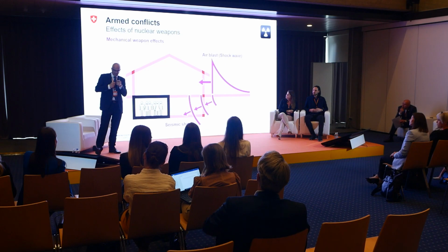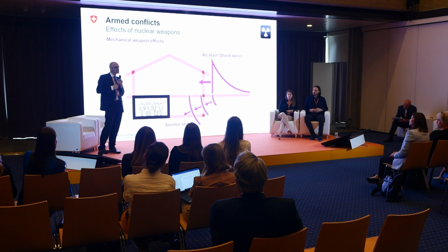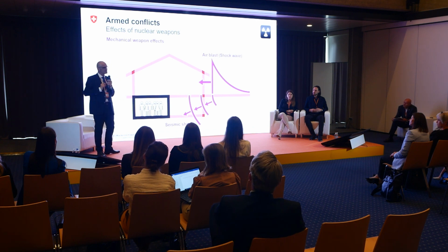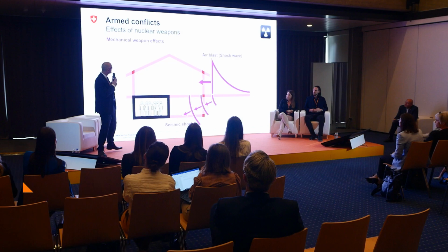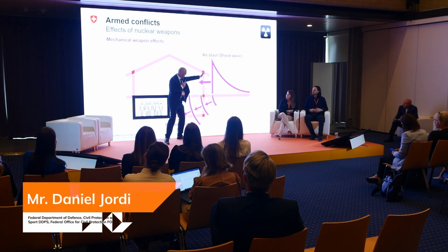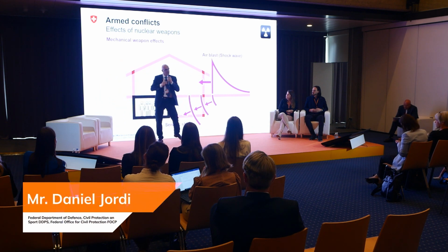The whole shelter remains intact in a ground shock due to this 100 kilonewton per square meter, which means it will be displaced in the ground by 20 centimeters. But it still holds for this induced seismic shock. That's the shock induced by the air blast wave, which induces its energy into the ground.